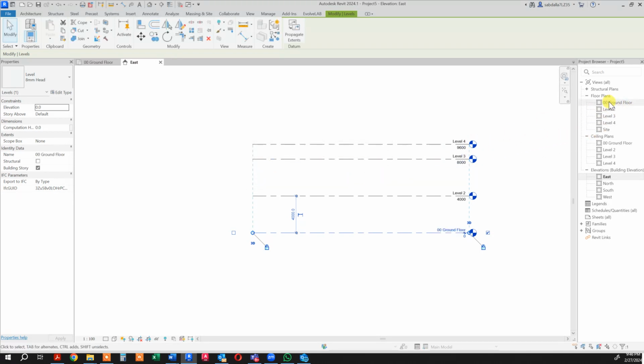Look at the name change here. I just want to hit the name itself. And the second one will be 0, 1, because this is like a database platform, so all the time they come on top of each other. If I name them ground floor, first floor, they will be arranged alphabetically, and then you get lost. So now I add this number.